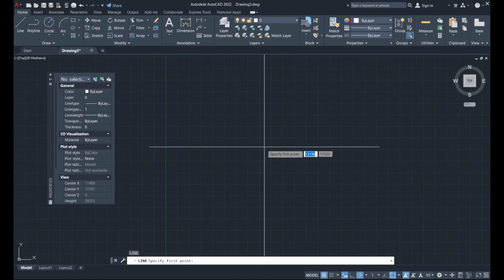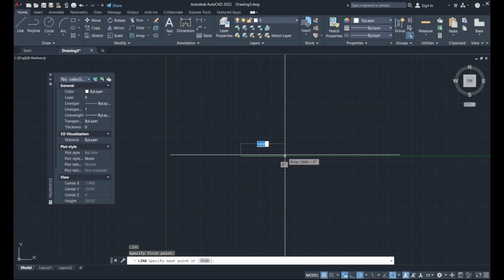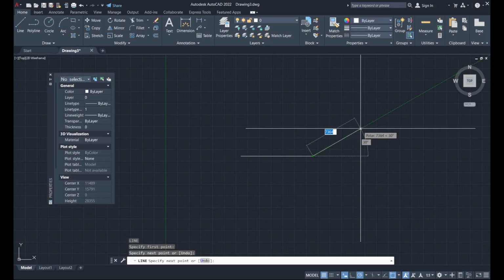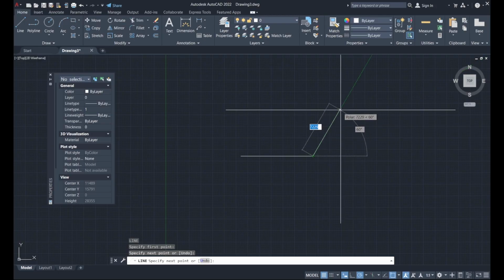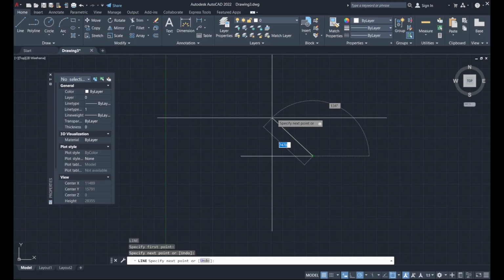Now let's draw a line. Now if we select a point and move to the right, it's showing this green dotted line. So this polar tracking sort of helps you snap your lines into angles. Now I have selected that point, and now for my next line, because I moved my mouse at an angle, it's asking to snap it at 30 degrees. If I move it a little more, the green dotted line is going to help me snap to 60 degrees, 90 degrees, 120, and so on.